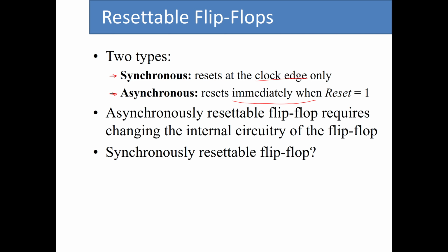So based on these differences, there are different ways to design these two types of resettable flip-flops. For asynchronous resettable flip-flops, you need to make some changes to the internal circuitry of the flip-flop. But for the synchronous resettable flip-flop, the design is very simple. So you might ask, how can we do that?